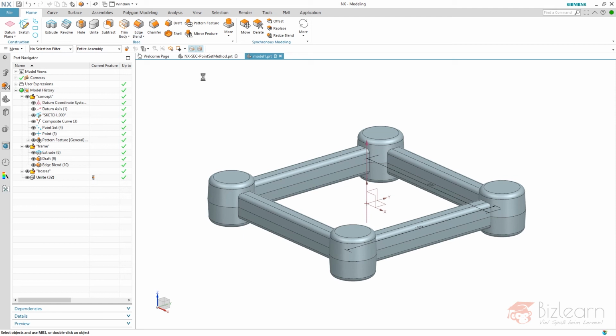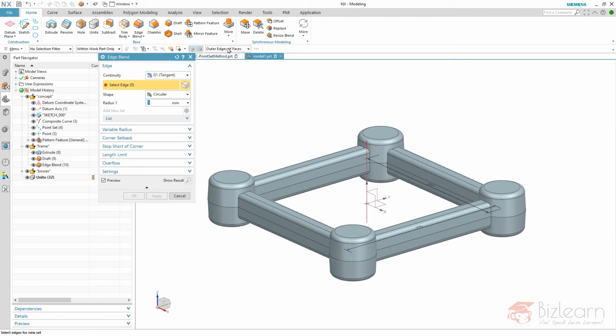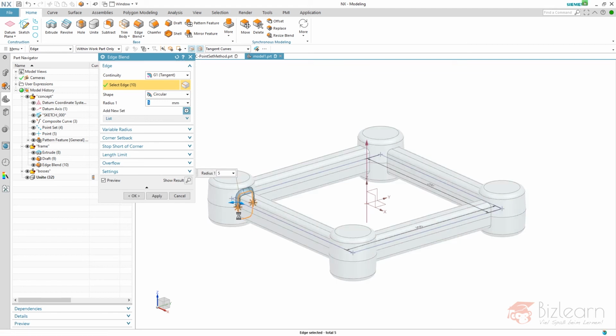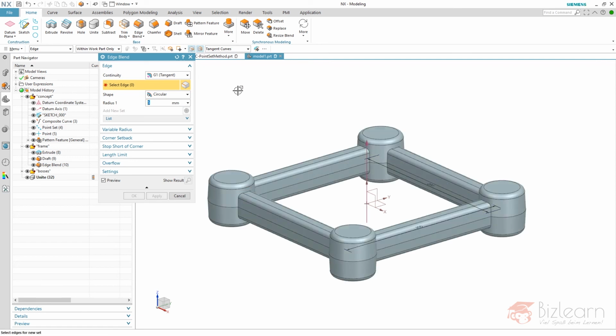And there's a pretty nice selection rule called feature intersection edges. And also here, the question is how to do horizontal modeling. What shall we do? Of course, you could use tangent curves, once, twice, etc. But also here, it's a relation to the newest objects. The newest object is the edge, which is a result from my unite. And you should be searching for something older. And there is a possibility called feature intersection edges.